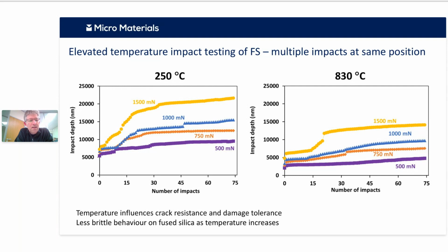What we can see here is at 830 degrees C, here on the right, it's more crack tolerant essentially, so there are more impacts needed, and the progression, once there is a bit of cracking, is more gradual than it is, more sort of abrupt and sharp, on the left.